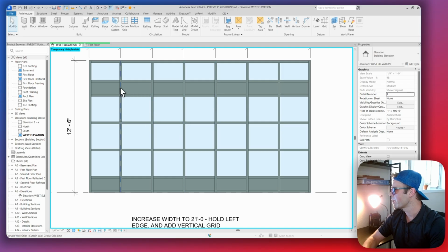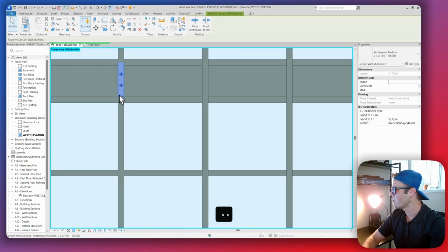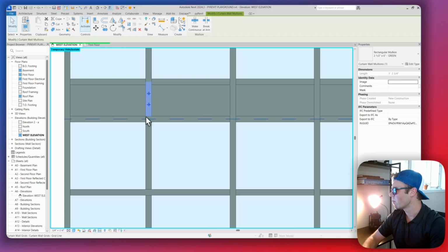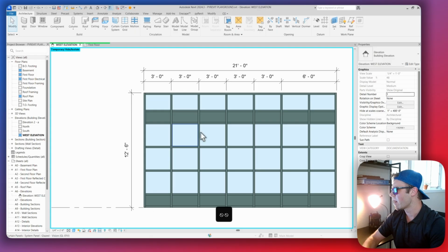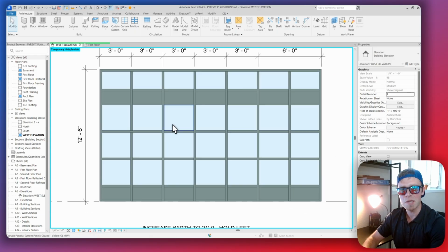It looks like just this grid here. See how the vertical mullion stops? We don't want it to stop. To fix that, we just select this mullion and hit this little crosshair, toggle mullion join, to join that. Okay, those crosshairs can be tricky. If joining mullions is giving you trouble, go ahead and just delete the mullions above and below or around there and reinstate them basically, and a lot of times that will fix that issue. Okay.